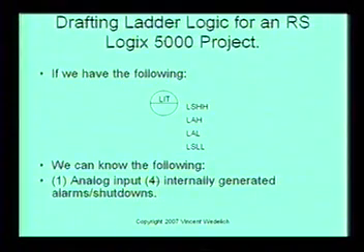You're going to overflow the tank, you're going to spill fluid all over the place. You don't want this to happen. If you have a level switch low-low, you're going to drain the tank. And if you drain the tank too low, you're going to starve the centrifugal pump of water and you're going to destroy it. It'll just destroy itself.